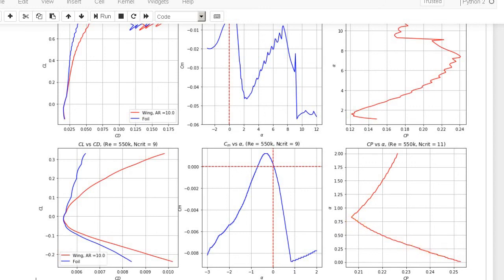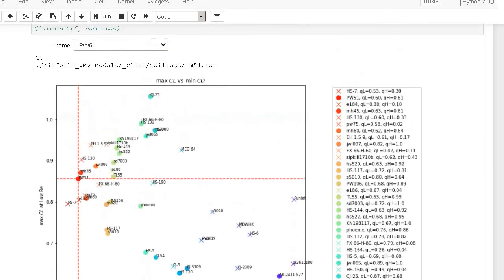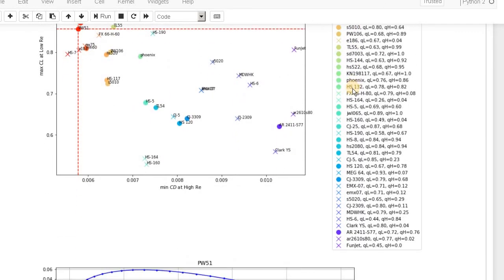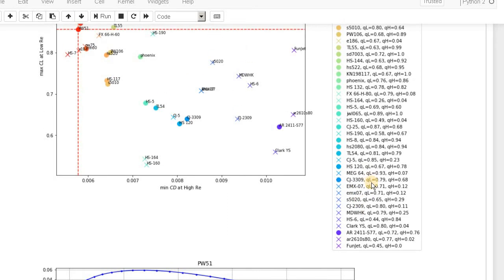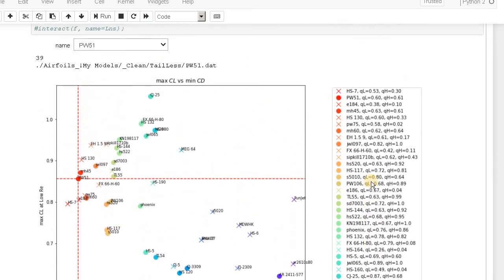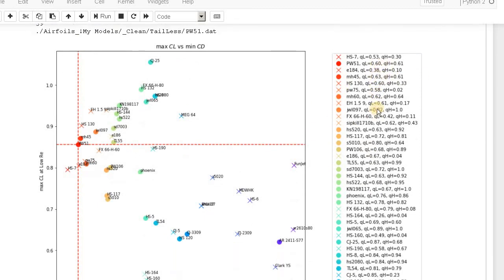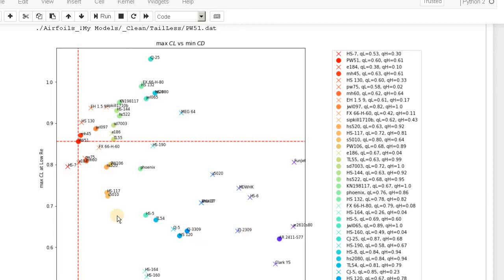If you go back to the previous graph, you can see that plenty of those beautiful airfoils that people have claimed to design for flying wings and tailless airplanes are unstable by their nature. And if we introduce more strict rules, we're going to have only 4 stable airfoils among all of them. So this is not good, and it would be nice to find a solution for it.